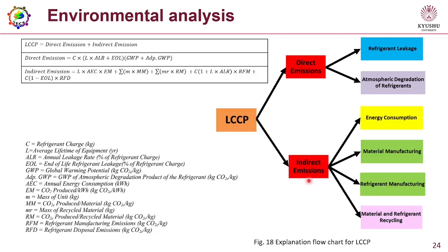In the indirect emissions, it accommodates the energy consumption emissions, the material manufacturing emissions, refrigerant manufacturing emissions, and the material and refrigerant recycling emissions. So LCCP is the sum of all the direct emissions and indirect emissions, and it is called a cradle to grave CO2 emission analysis. These are the formulas for calculating the direct and indirect emissions.